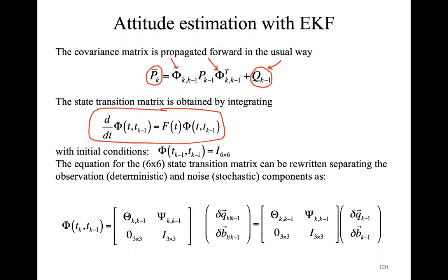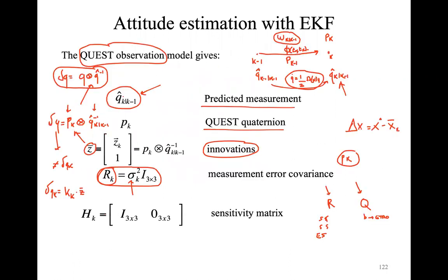Let's try to do that, with a diagonal matrix similar to what you have for R that accounts for the errors of the star trackers, and see what you get. That's my suggestion, but it is only for academic purposes, of course, and also to better understand how the tuning of a filter is done.